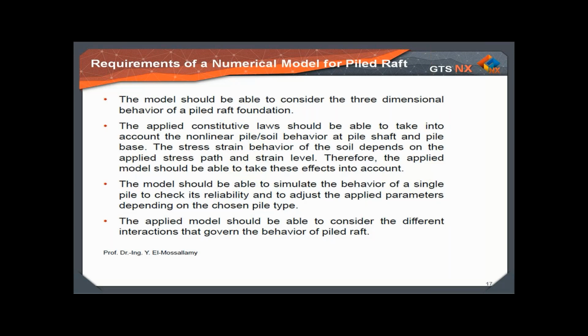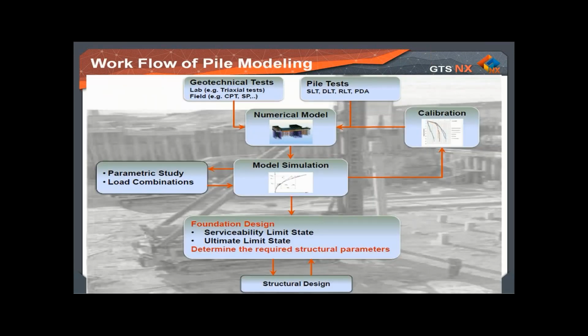So, if we have results from a pile loading test, you should be able to simulate this pile loading test properly in your numerical tool. And then once you are able to capture the behavior you have in the pile loading test, you can go back and utilize these parameters in your full structural numerical model. The applied model should be able to consider the different interactions that govern the behavior of the pile raft, which we just saw in the slide.